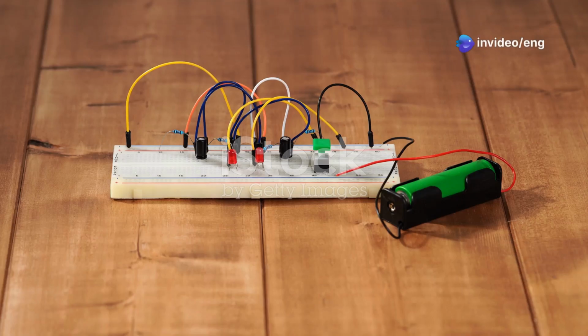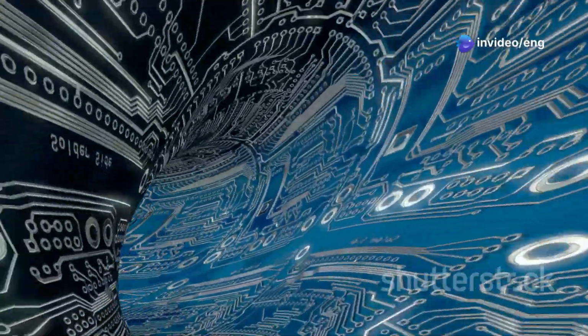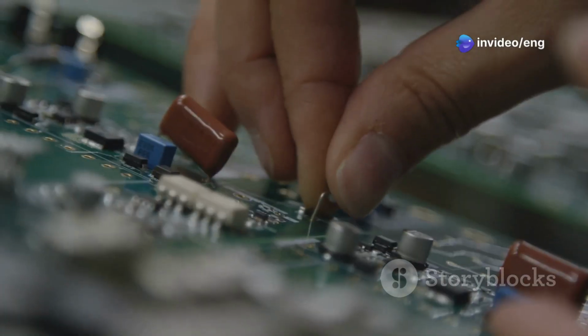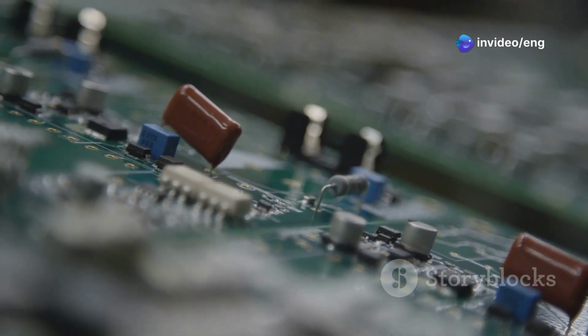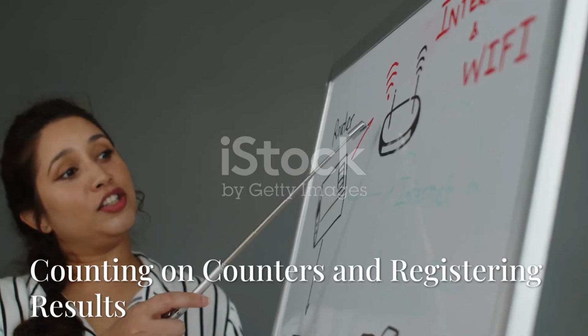Next up is the D latch. Like the D flip-flop, it has one input and remembers whatever value is on that input. However, the D latch's output changes immediately when the input changes, just like the SR latch. Latches are often used in situations where we need to quickly capture and hold information. They're like the quick reflexes of the digital world.